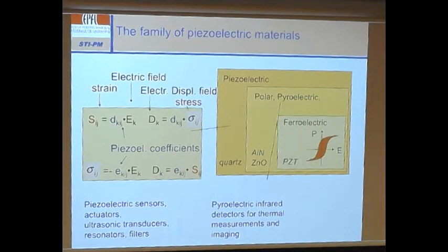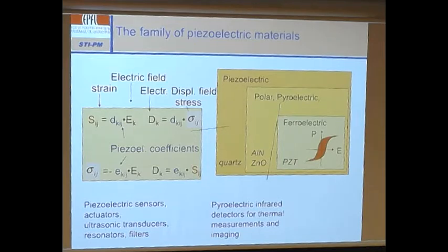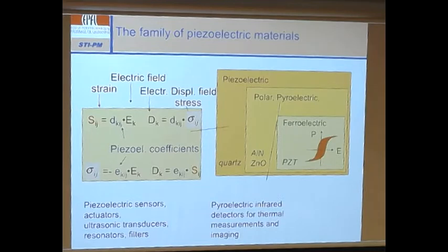I think still in many vacuum tools, you will find contactless pyrometric temperature sensors. So it's one of the standards there, in fact. But for infrared imaging, they lost the battle. It's much cheaper to make sensors based on semiconductors, which have a very strong resistance variation with temperature.